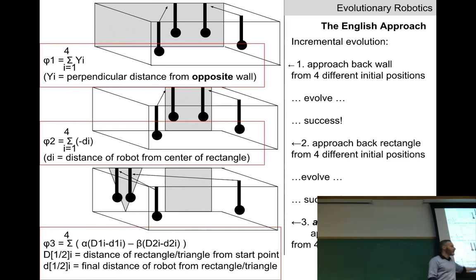They had to put alpha and beta in here to tune these weights a little bit because the robot was a little bit jerky, and there were some other reasons for it. Doesn't matter for our purposes, but this might be useful for you later if you want to reward something very strongly but provide a mild penalty for something else. You can have a big alpha and a small beta. So you can reward and punish for different things and tune how strongly you reward and punish different things. So far, so good?